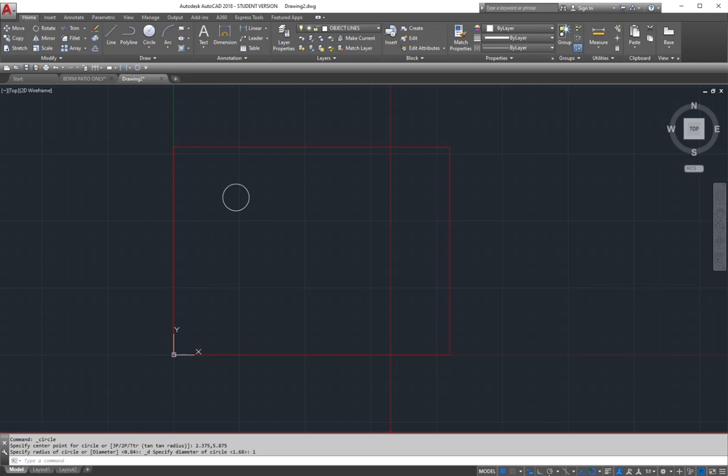And I'm going to activate my ortho. You can see under the status bar that I can have my ortho on. It allows me to go vertically or horizontally only. And if I wanted to go under polar, then I can go in this symbol, my F10 or my polar track, and I just click right here, and I can always select any of my angles, my increments that I want, 5-degree increments, 10, 15, 18, and so forth. So I'm gonna leave it at 45 for now.